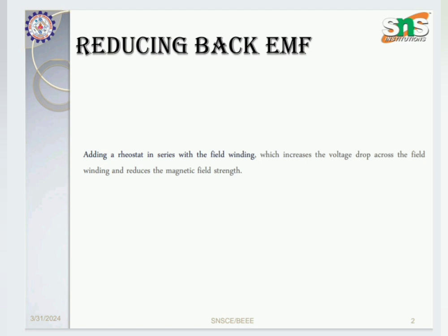On the other hand, if there is no mechanical load on the motor, it will increase its angular velocity omega until the back EMF is nearly equal to the driving EMF. Then the motor uses just enough energy to overcome the friction. Now let us consider an example, where any rotating coil will have an induced EMF, and in the motor it is called the back EMF since it opposes the EMF into the motor.